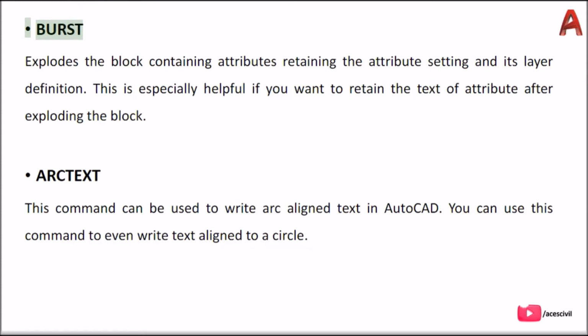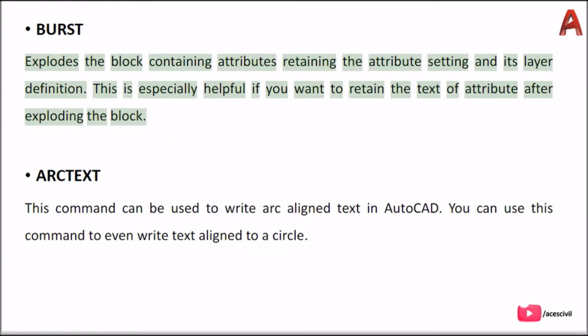Burst. Explodes the block containing attributes, retaining the attribute setting and its layer definition. This is especially helpful if you want to retain the text of the attribute after exploding the block.